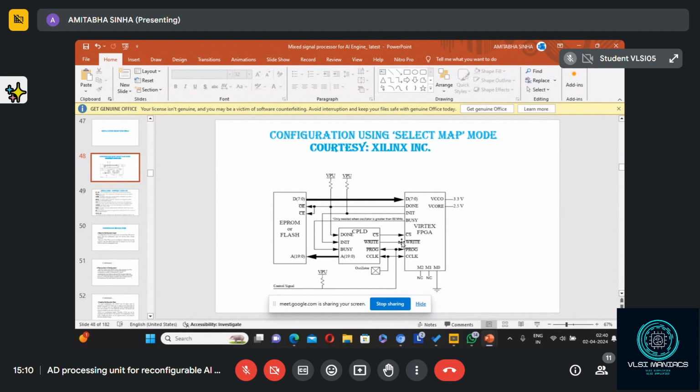So these are the major pins. Another is done and busy. Busy means when it is being programmed, it will be busy. And when it is over, then it will give the done signal, meaning it is over. For example, 1 byte has to be downloaded. Each time 1 byte is downloaded, once the download is complete for that byte, it will give a done signal to indicate that it has been done.